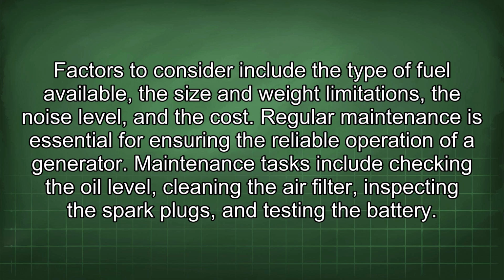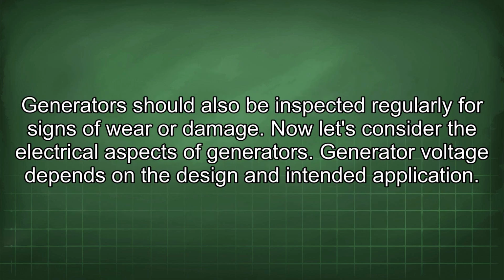Regular maintenance is essential for ensuring the reliable operation of a generator. Maintenance tasks include checking the oil level, cleaning the air filter, inspecting the spark plugs, and testing the battery. Generators should also be inspected regularly for signs of wear or damage. Now let's consider the electrical aspects of generators.